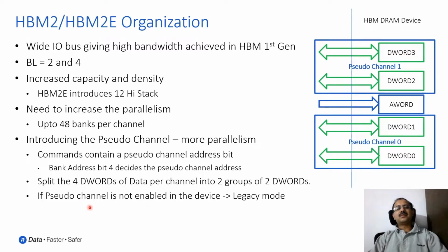And of course, for backward compatibility, what was done is, in the case where a pseudo-channel is not enabled in the device, then it could still operate in the HBM1 mode, the HBM legacy mode. So that was allowed in HBM generation 2.